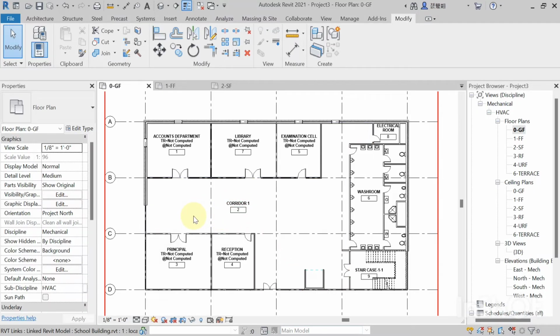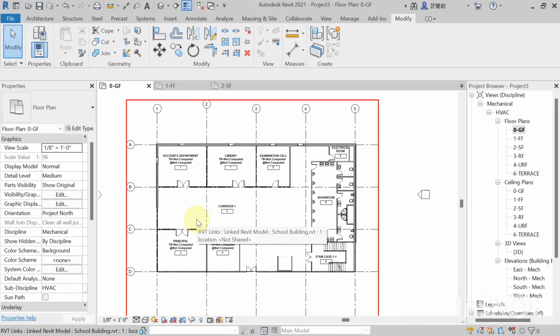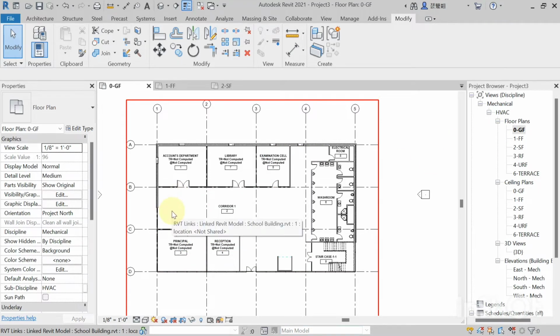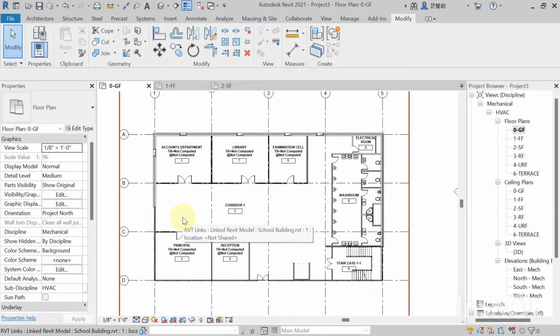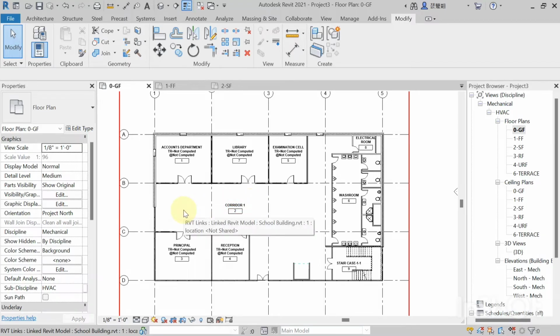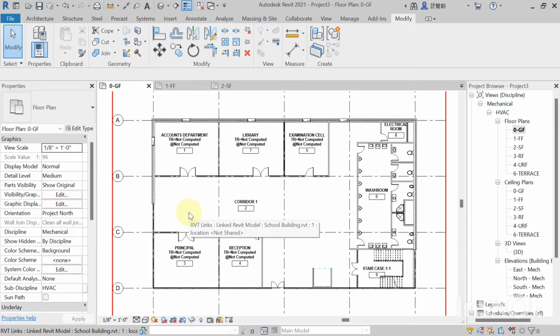Suppose let's say here I am using only one AHU which we have to place above the roof. I am planning for my project. So with the help of one AHU only, we have to supply the conditioned air in ground floor, whatever space is there, in first floor space and in second floor space. You can do it like this, or separately. You can select a separate AHU for ground floor, a separate AHU for first floor and second floor. If you want to use the FCU, ceiling suspended FCU, you can use that also. So here I am just planning that I am using the AHU.